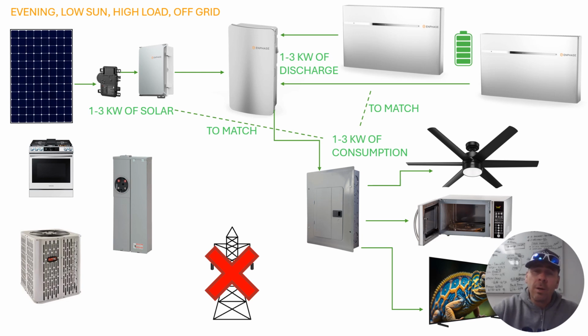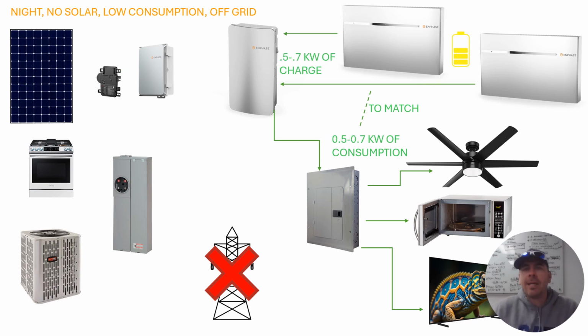Right? So you'll be able to pull power from both the batteries and the solar while all the grid is out and everything else is not functional. All that stuff will maintain and manage itself, ramp up how much power comes out of the batteries, ramp it down based upon how much power you're using and based upon how much solar is present as well. So it automatically, instantaneously collects all the data for your power usage and makes it ready and available for you to use. Here's the night diagram. Now the sun is down. Now it's just the battery regulating the power for having the available power for you to pull power from the batteries at any time to take care of your loads that are on the backup system.